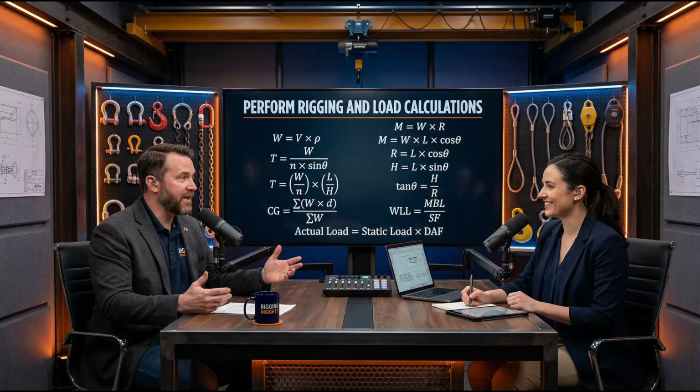In crane terminology, this is the exact same concept as the load radius. Because the further away it is, the harder it is to lift. Exactly. The further the load is from the center pin of the crane or the human spine, the less capacity it has. And the asymmetric multiplier measures how much the worker twists their torso while holding the weight.